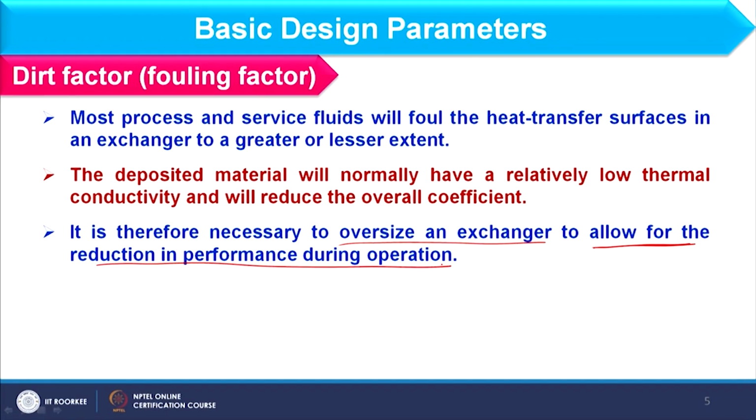Whatever surface I consider, it will have scale formation during operation. If I oversize the heat exchanger, the dirt formation will still be there, but it will occur over a longer time as compared to a lesser heat transfer area.